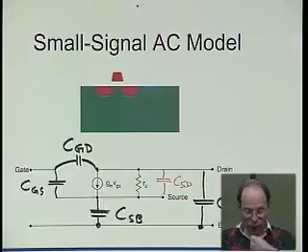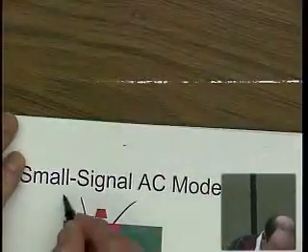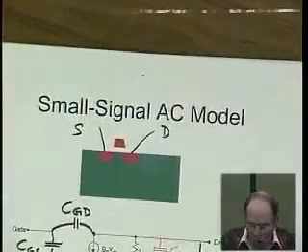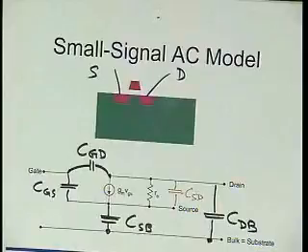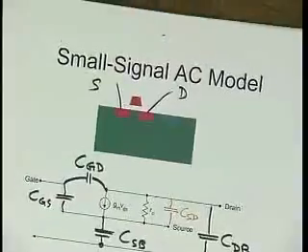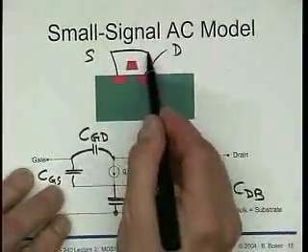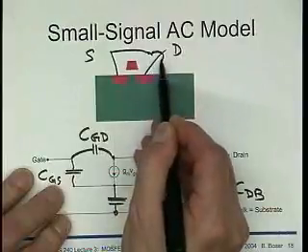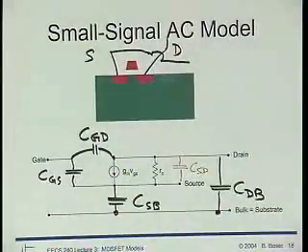And of course, if you look at the transistor, we have a source and a drain, and they don't overlap, and so the capacitance between them ought to be pretty small. And if we lay out the transistor right and so on, lo and behold, it is. Be very, very careful because then you wire up this device and you build a nice little bridge and crossing here, then it's no longer 0.